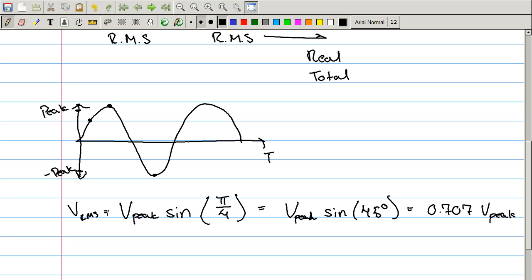RMS voltage is, say you have a resistive element like a stove, and you pass 120 volts effective voltage AC through it. If you were to pass 120 volts DC through it, you'd see the same current as you did in the AC system. That's what the RMS, or effective voltage, is. Effective voltage is also what most multimeters that will read an AC voltage measure.